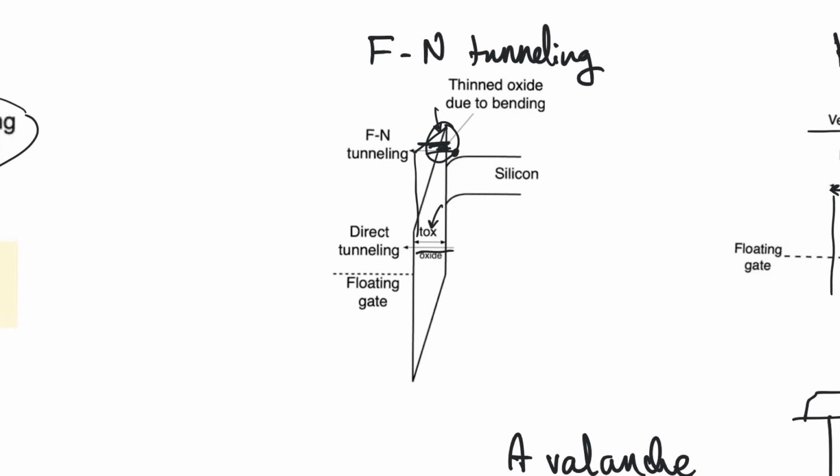Now, what are the advantages of tunneling? It's very gentle. The electrons are not actually passing through the oxide. It's a quantum effect. So it has great programming cycles. It can also be used for programming or erasure, because we're not depending on the electrons being hot. We don't want them to be moving. We don't need them to be moving. They can be still, and they will still be able to tunnel to the other side. So we can actually use this for erasure. We can actually use it to pull electrons back into the substrate from the floating gate.